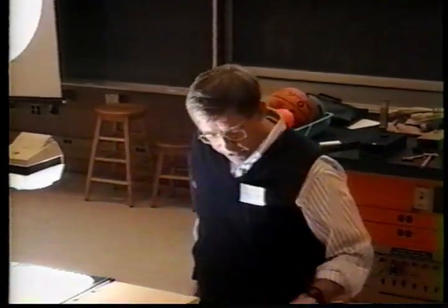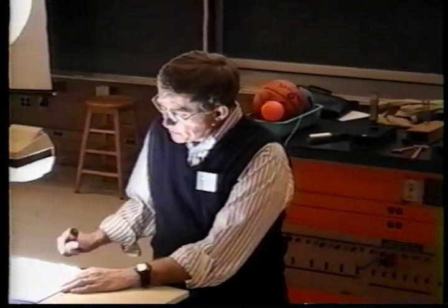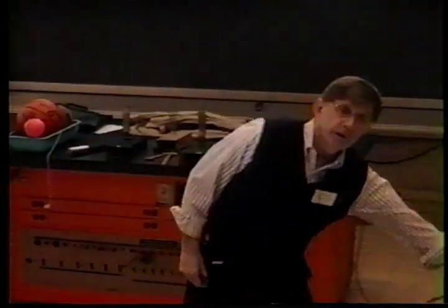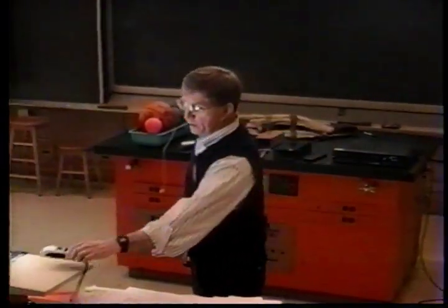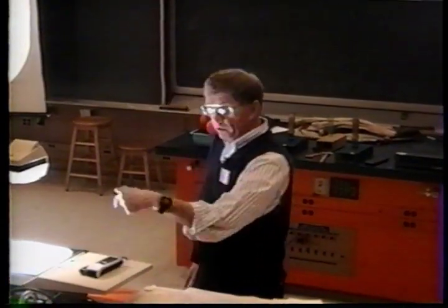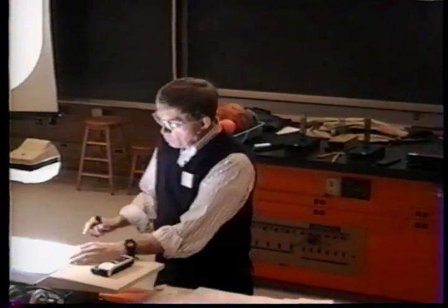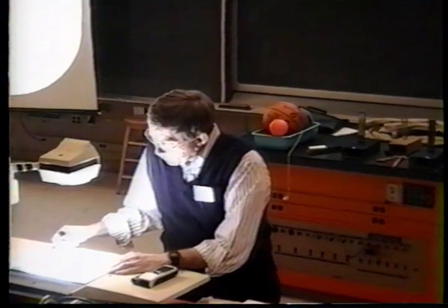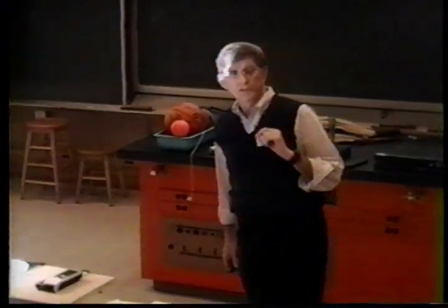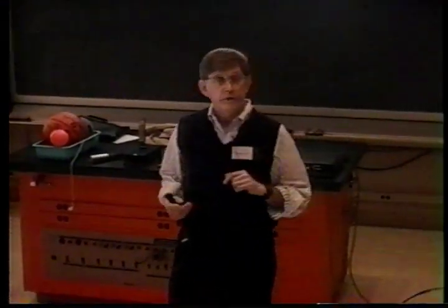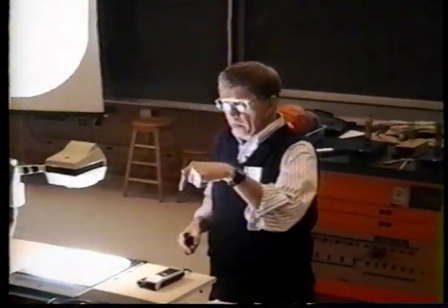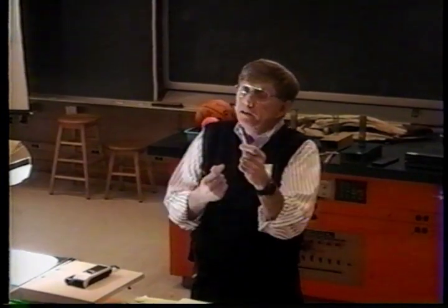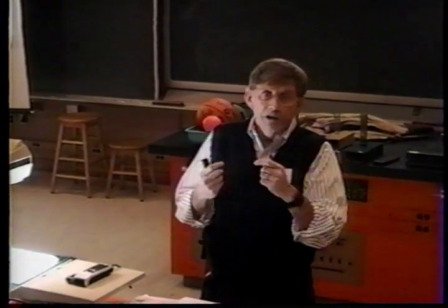Okay, the last thing I want to say is what differential GPS is. Suppose I place a standard receiver at the end of the runway at O'Hare Airport, and I have a person or a machine reading where the receiver says the end of O'Hare Airport is. You're coming in on your plane with a GPS receiver, and I send you a radio frequency signal saying the GPS unit at the end of the runway where I'm located is giving an error in the X, Y, and Z directions of a certain amount.